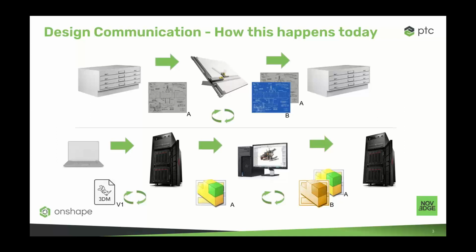Some systems will let you import a Rhino file, but then it will be converted to another file type. It'll be converted to the mechanical CAD format, whether it be Creo, Inventor, or SolidWorks, all the common ones that are out there, right? So you do your design changes here in the mechanical system for design for manufacturability. You're going to add fillet radii, draft angles, designing it for the manufacturing process at hand, going from conceptual design to true design for manufacturability.